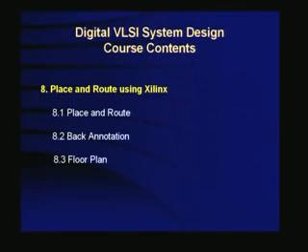And there will be errors, and you should know how to handle them. ModelSim may give errors, and in this synthesis process also you may have errors. When errors occur, how do you handle them? Then after having synthesized it, you are ready to map it onto a device, an FPGA device. That means you have to place it, placing the various components within a field programmable gate array, and route it. Place and route decides which functional blocks within the FPGA we are going to use for realizing the specifications of the required circuit, and how you are going to interconnect them, that is routing.